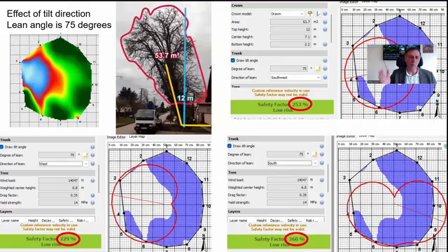There was an opening we were able to see visually, and the acoustic tomography reflected well the feature we've seen visually. And the leaning angle relative to the vertical was 15 degrees, or in our scale relative to the horizontal is 75 degrees, unchanged.